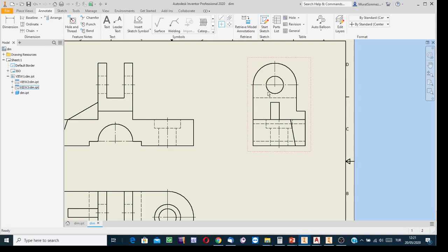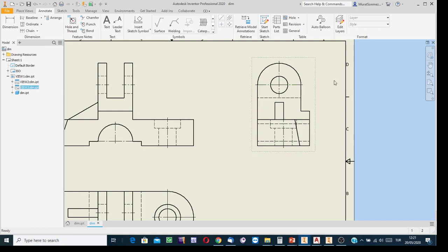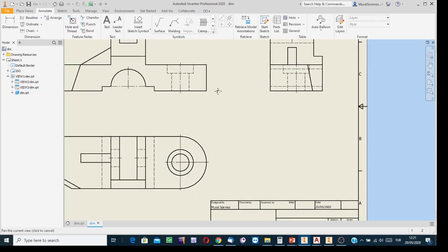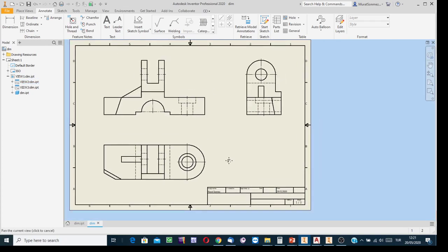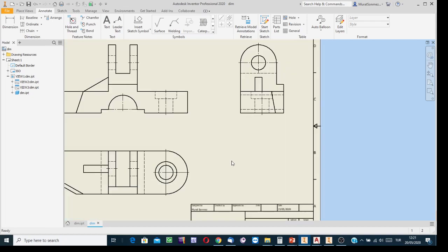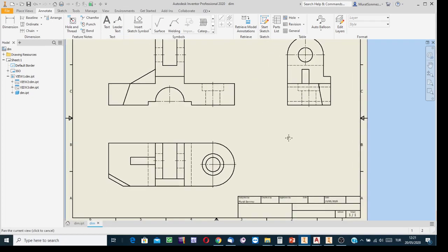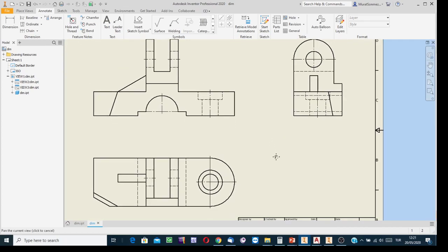use the stretch technique. Otherwise the symmetry axes may coincide onto each other, and the short dash may clash with the long dash, and the line may appear as a continuous thin line. So it is a poor practice. Okay, so we managed to show the axes of symmetry, and then the rest is dimensioning.